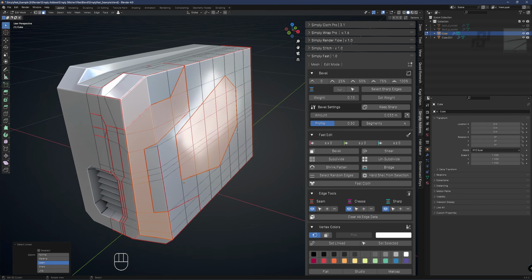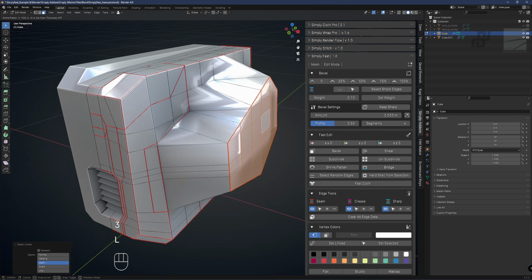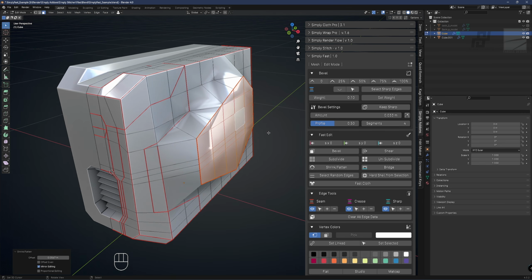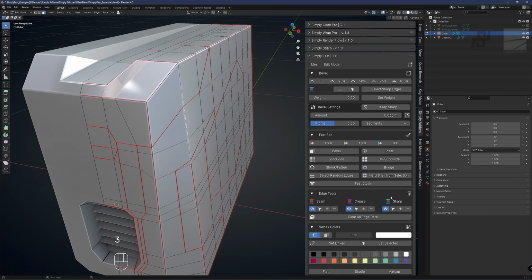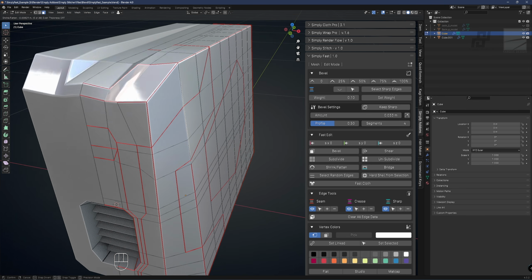It's a bit too much. So very easy, select, hit this button and do it in the normal. So it will scale it by the normals. I think you will notice it here more. Yes, so it goes up.